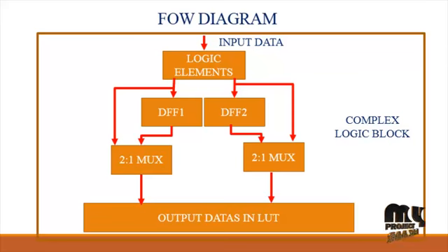After that, the output of the logic element is fed into the D flip-flop. Before that, what is a logic element? It is the smallest unit of logic in the Cyclone 3 device family architecture. It is compact and provides advanced features with efficient logic usage.